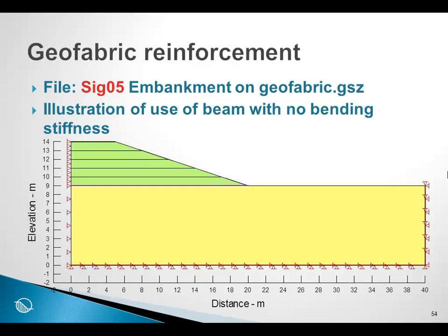Now we will use a beam element to simulate the effect of a geofabric. A geofabric can withstand tensile force, but no compressive force, and the impact of the tension in the geofabric will alter the stress state in the ground underneath an embankment, for example.